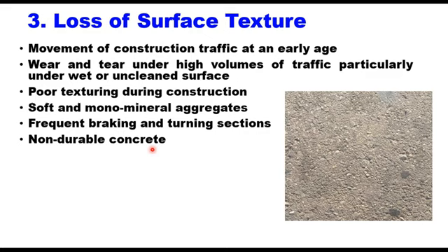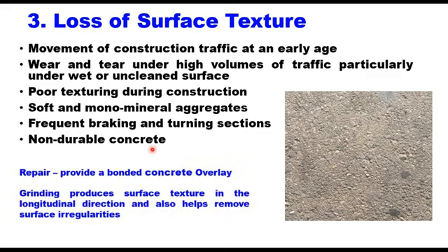To improve the surface texture, either you provide a bonded concrete overlay or grinding can also produce surface texture in the longitudinal direction, and it can also help remove surface irregularities, means roughness also.